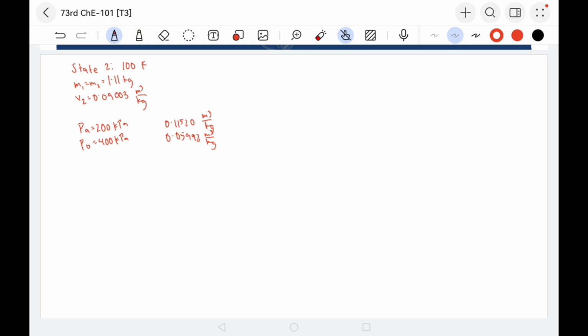Upon interpolation, which I will skip in this video, you will get a P2 of 291.06 kilopascals. For the internal energy, the corresponding values are 71.73 kilojoules per kilogram for 200 kilopascals and 69.30 kilojoules per kilogram for 400 kilopascals, to get a U2 of 70.62 kilojoules per kilogram.